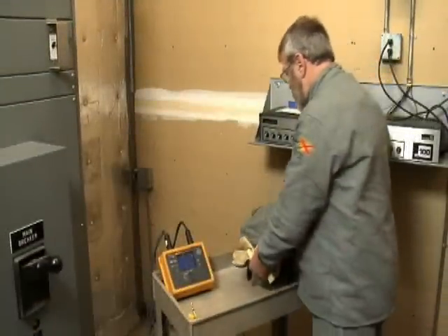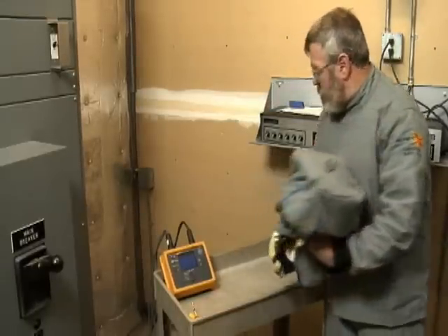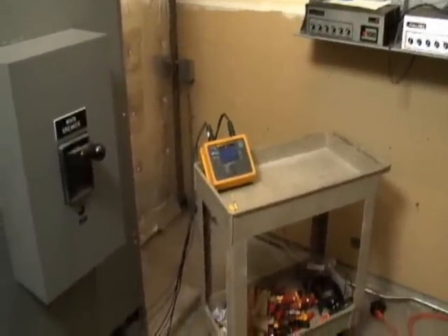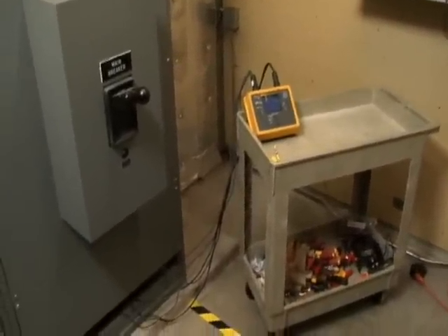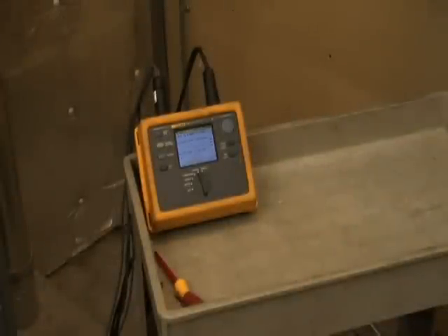Start recording and walk away. You want to capture the full demand cycle if at all possible. In particular, we want to use less energy at times when it's the most expensive. But we also want to see how much we're drawing during the middle of the night to see if there are things we could shut off, and see what our power draw looks like when multiple loads are working simultaneously. Later on, we'll use this data to see if we can change our operation to use less energy.